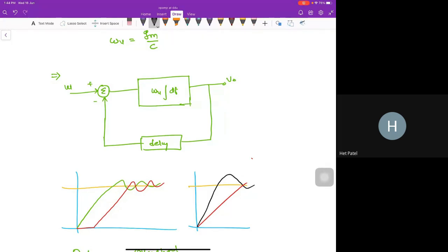And if you analyze those poles and zeros, even in control systems, you can see that a first order system is always a stable system. But if you go for a second order system, although it is a stable system, if I don't have control over some parameters, zeta and omega n, which we will see, then my pole location is different, and I will get an underdamped response, that is a ringing, and that ringing is undesirable, and that ringing is here. So I am relating that second order system with delay and that pole. I think you got it clear.